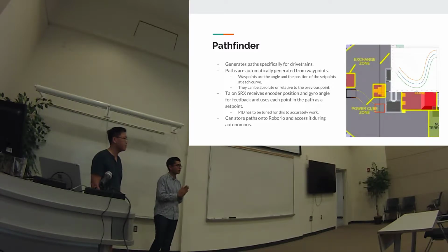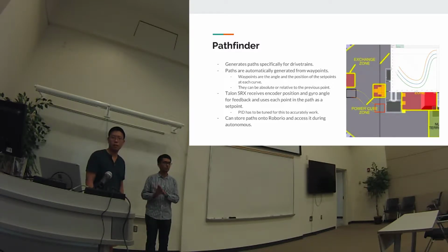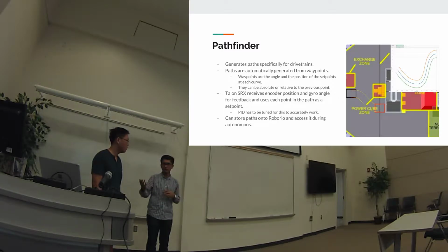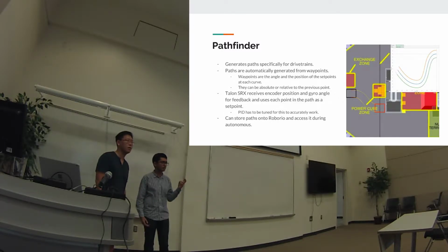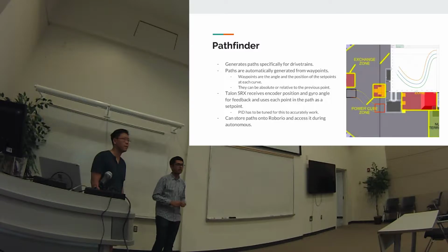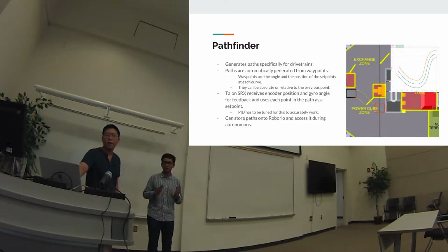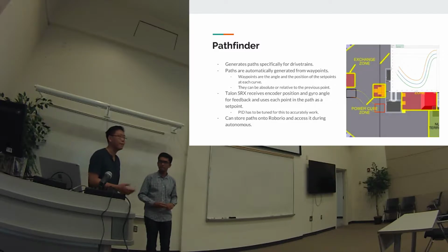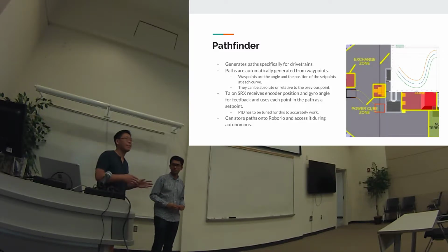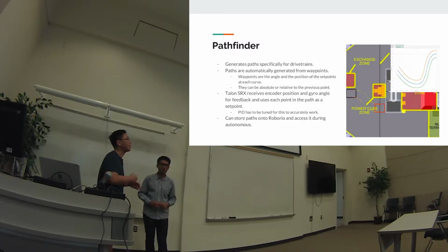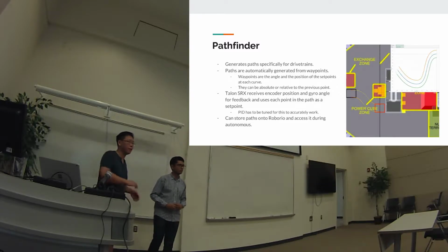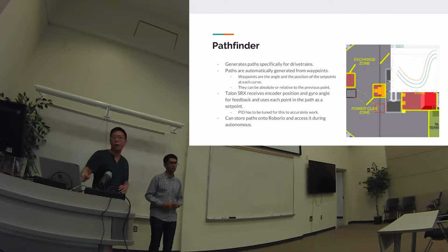One thing to always keep in mind when doing this is that there's always a frame rate, or in this case it's the DT, which is the variable used in the code. Yeah, your time step. Basically, that's the time step between each position that it goes to. Right. And if we go back to the PID controller, it's your DT, right? Because when you're computing, it's basically a different way to calculate the integral and your derivative. So you use your DT as your time step when doing that.